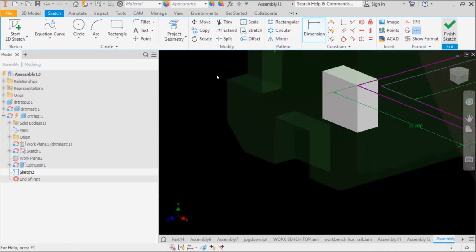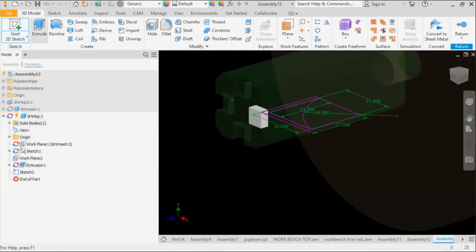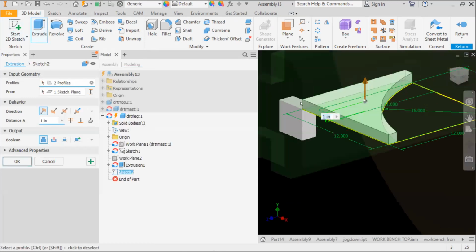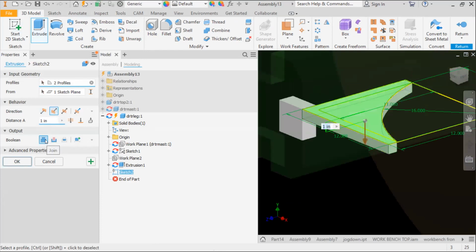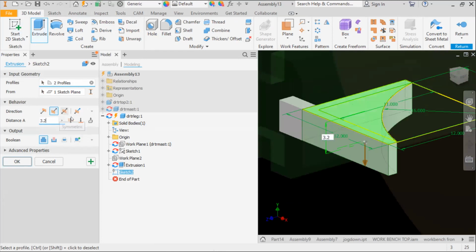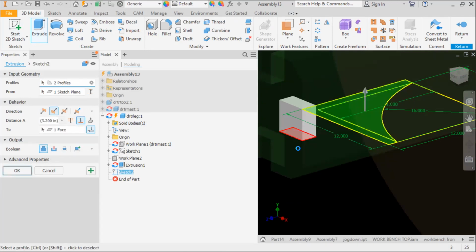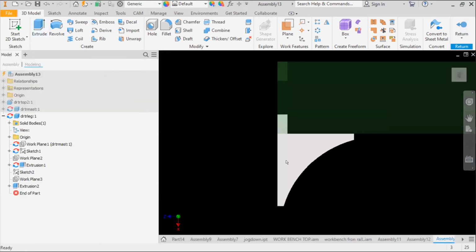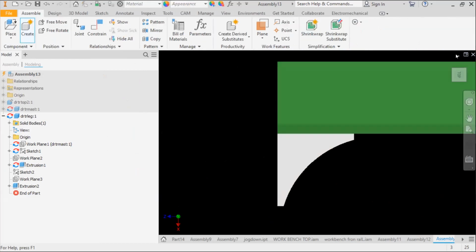I'm going to click Finish Sketch now, and I'm going to extrude this shape and this shape down to the other side of that. I'm going to invert my direction here. I'm going to make sure I'm actually producing material. And I could input my thickness there, which should be 3.2. Or, as I'm really trying to push you to do, use the To tool and just click on that bottom surface. There. Now we have a nice table leg that has kind of ended corners so they don't come to a point and break off when kids are wrestling underneath the dining room table at Thanksgiving.